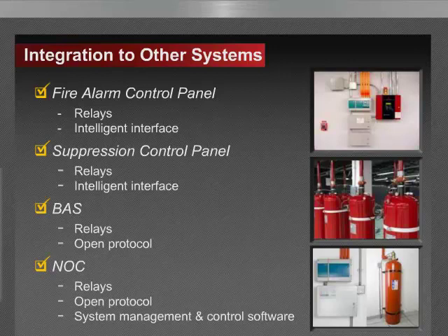So no system would be complete without tie-in to other systems for signaling of alarms, reporting, and management of the installation. Multiple paths are possible, and the method of tie-in largely depends on the capability of other systems. Advanced aspirating smoke detectors can provide connectivity through relays, intelligent interfaces with OEM equipment, through open protocols for a more customized level of reporting, or through manufacturer-provided system management and control software for management of a single or multiple networks, either on-site or remotely anywhere in the world.